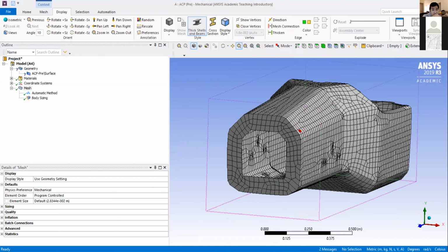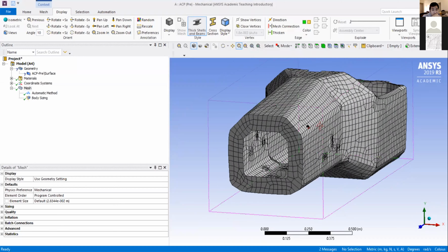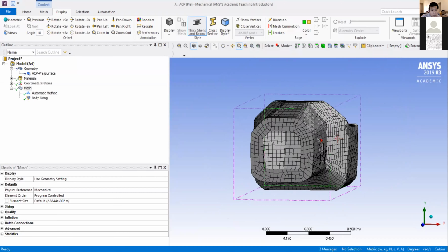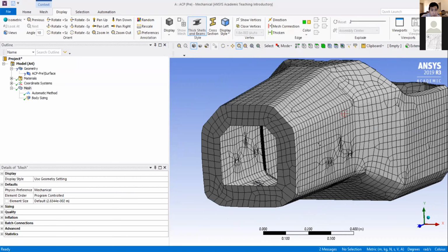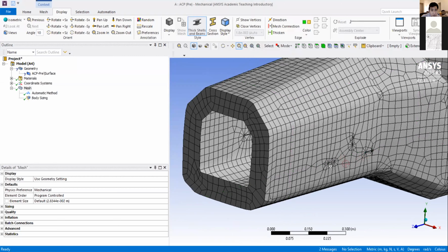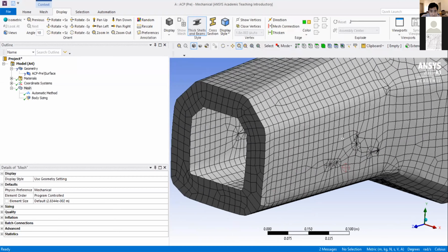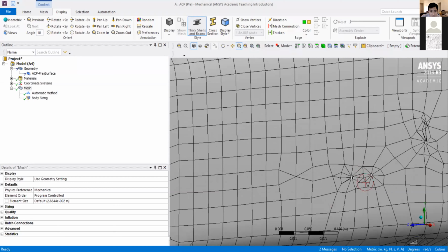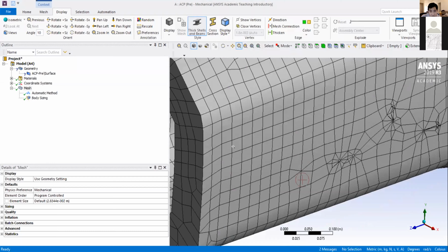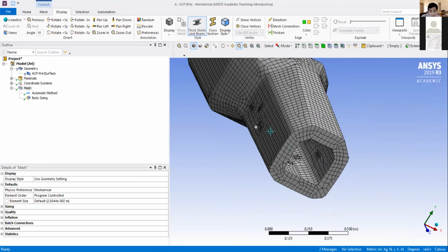So far, I have to kind of induce a moment on this. I'm just trying to figure out how to do it. I was watching some videos online and their suggestion is, for example, you see these patches. These are holes that connect to our suspension system. I don't know if it would be adequate to apply a load on all these holes up, and then the other side of the chassis, it would be down. So it would induce a couple.